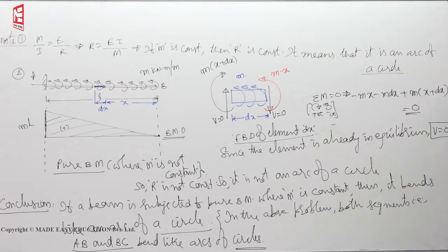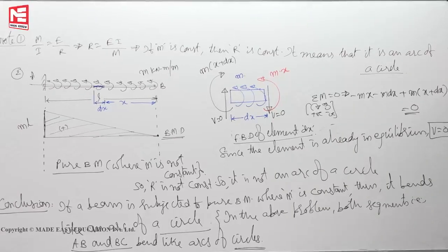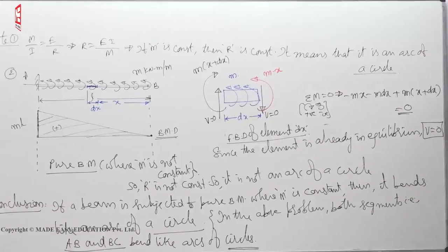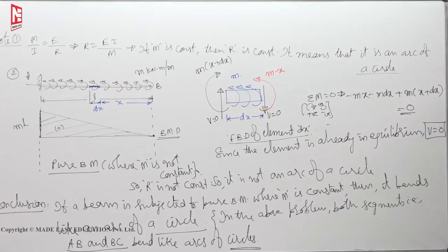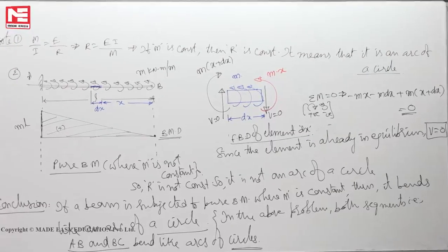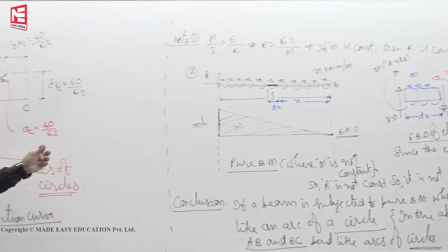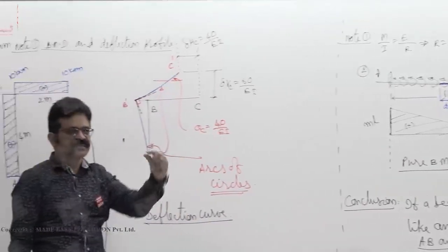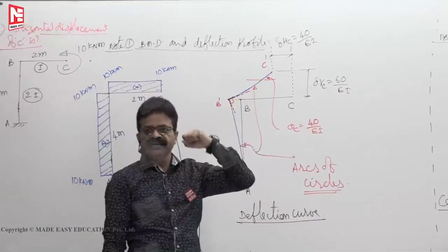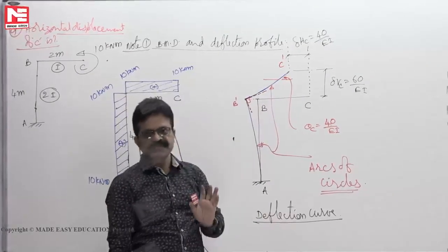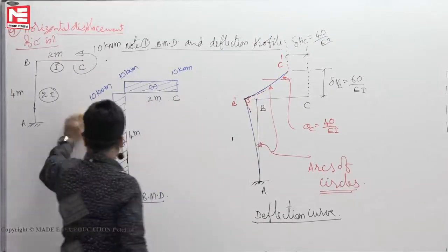Now, it is not necessary that we should have a straight member. You can find bending or deflections in curved members also. Then you have to take the strain energy stored in the curved member, not straight members. So accordingly, for the strain energy stored in the member, we should not write the elemental length dx; we have to take the curved element ds and find the energy and also the deflection. Let us see one such problem.